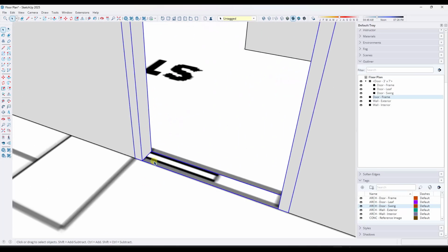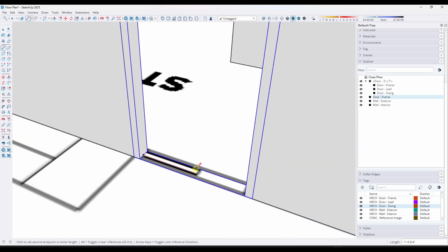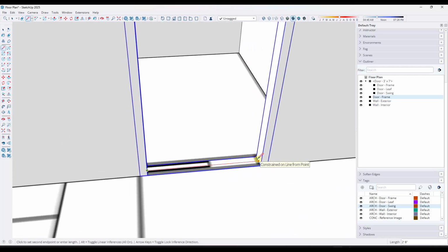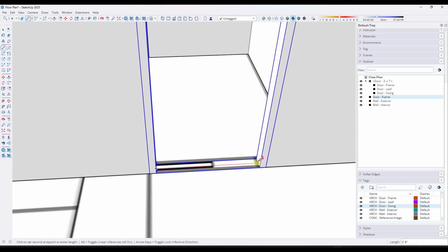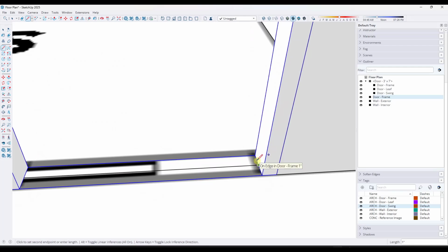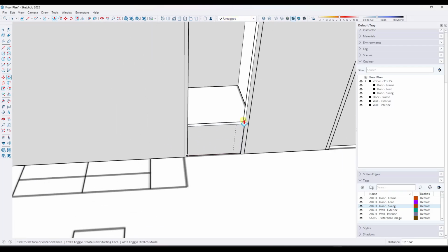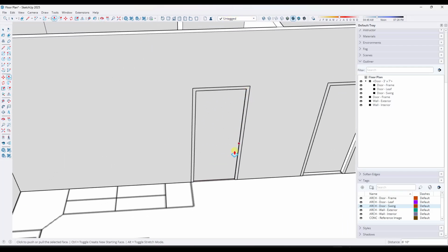And in this case, we've got a door leaf, right? And so that door leaf is actually going to fill in the space like this. For now, let's go ahead and just model it across this whole opening, right? So I'm just going to use the midpoint in the frame right here, and I'm just going to model a door. We'll just say it's going to be 1 inch wide over here, and we'll say it'll be 2 inches wide all the way across, right? So now I've got a full-on door, and you may need to redraw a rectangle over top of this in order to get this face in here, but then we're just going to pull this up like this.